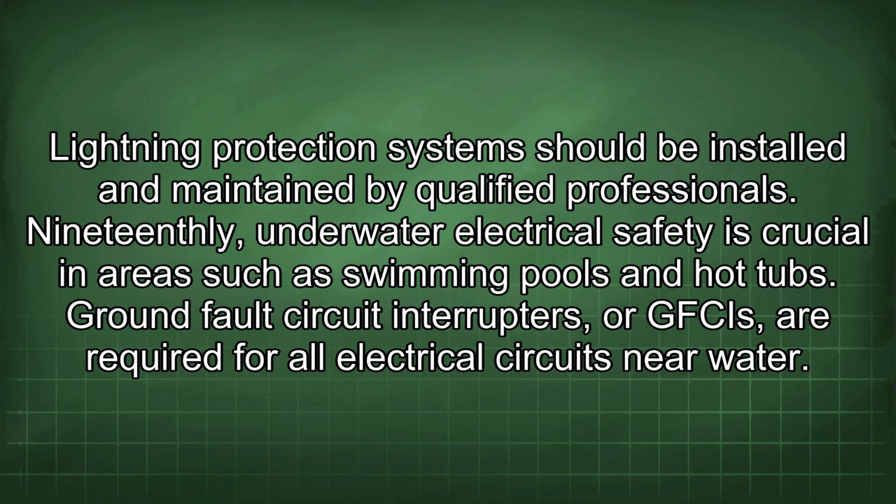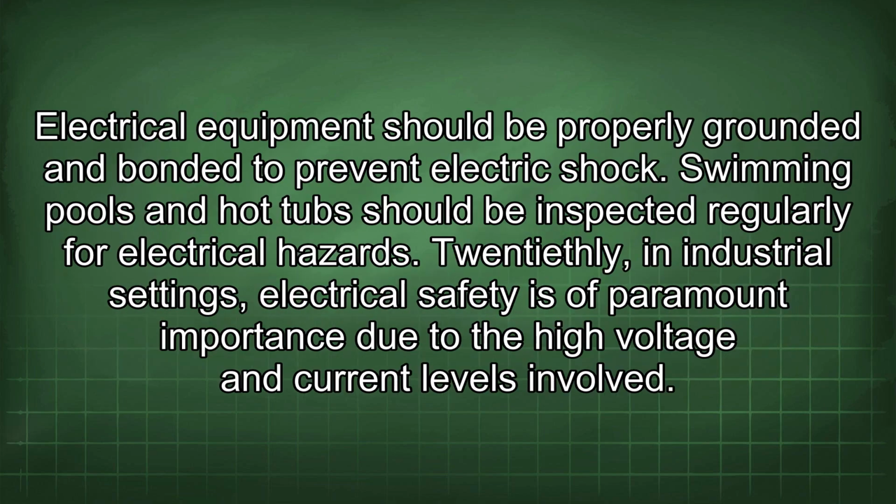Nineteenth, underwater electrical safety is crucial in areas such as swimming pools and hot tubs. Ground fault circuit interrupters, or GFCIs, are required for all electrical circuits near water. Electrical equipment should be properly grounded and bonded to prevent electric shock. Swimming pools and hot tubs should be inspected regularly for electrical hazards.